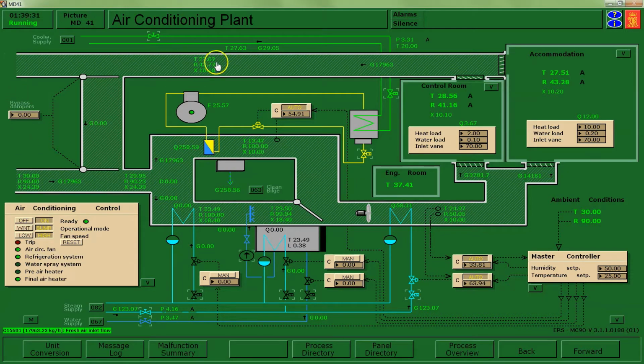If we just note what's leaving our system, it's about 27 degrees and 40% relative humidity. The air that we're drawing in is 30 and 90. This air is a lot closer to our set point, so it's going to be easier for us to maintain that air back to our set point in terms of energy consumption than it is for new air to come in.